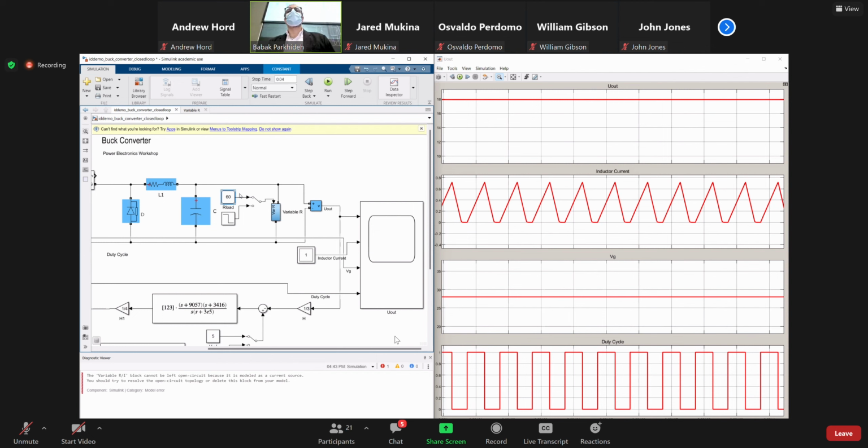I would think smaller. Yeah, exactly, smaller. Okay. So if you operate the converter in this discontinuous conduction mode, you would need a smaller inductor. Do you see any advantage? Smaller inductors are cheaper and smaller. Cheaper, and less space.